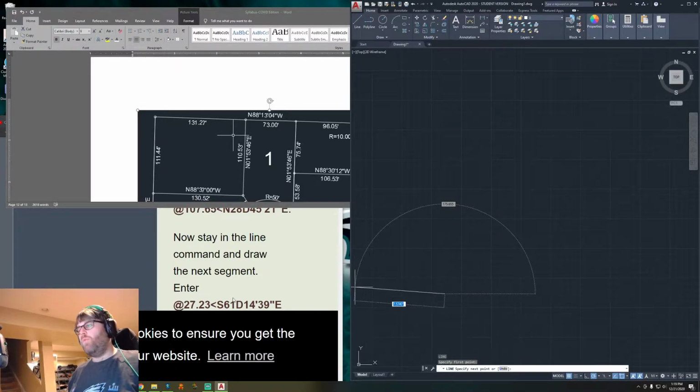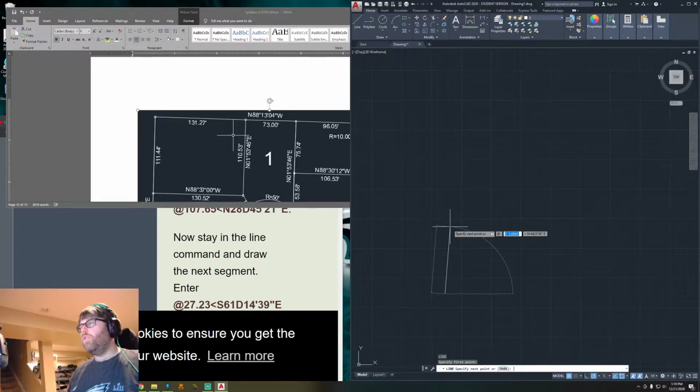Now this is where we will be following this here. So if we do an @ symbol, we will do 110.53. Don't forget the apostrophe because that says it's going to be 110.53 feet. Oh, thank goodness my video is not in front of that nomenclature. Cool. 110.53 feet. Then we do a less than sign. You'll see that it brought us to the right part, which is where we enter in our bearing.